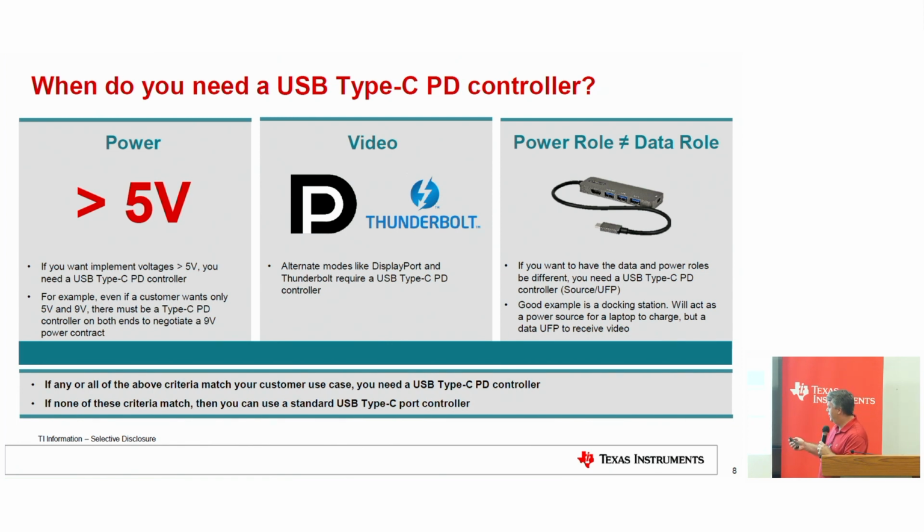And a point I didn't hit on before, another key benefit of USB Type-C PD specifically, is the ability to do power role and data role swapping. And power role and data role are not the same. If you think of legacy USB Type-A, the large rectangular connector that typically came off your old mouse and plugged into your laptop, that was one-way host and device.